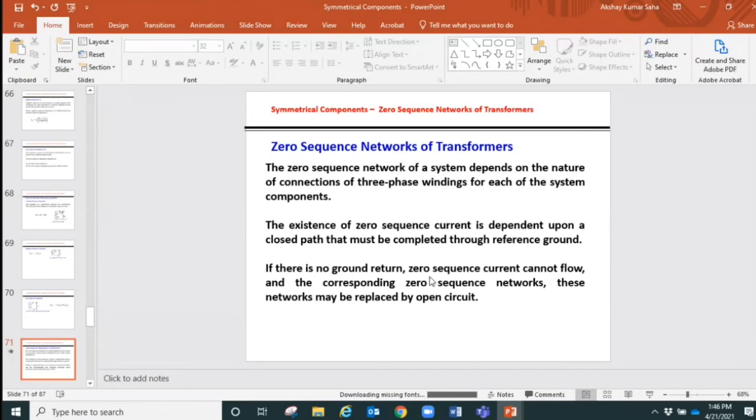And different configurations is what? We can have a transformer winding configured as star or delta, and again those star points can be left floating, connecting solidly to ground, or connecting to ground via an impedance. So all those things need to be considered for that particular connection type.